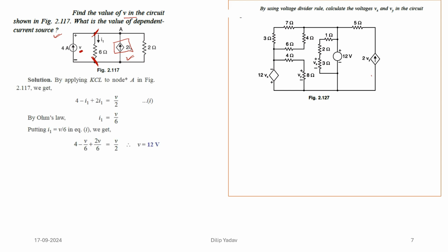We are going to solve it in a simple way, because we know the KCL, and by using nodal analysis. If I take the node analysis across this terminal, if this was given as 4 ampere and I1 was going this way, so I can say the current across this terminal will be 4 minus I1.